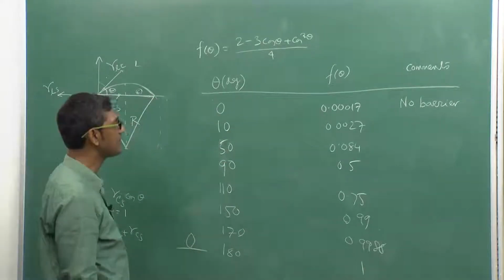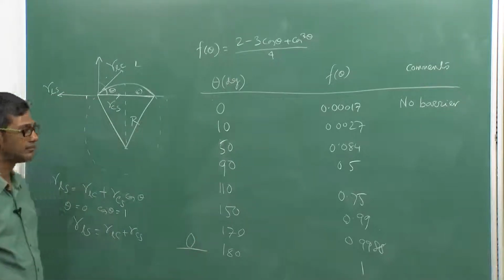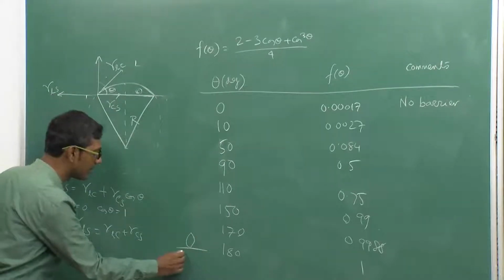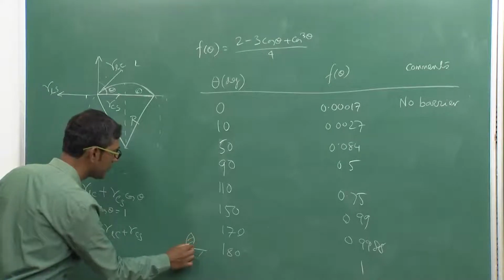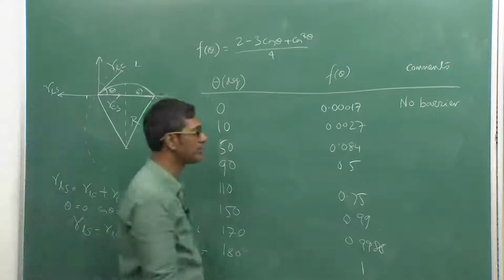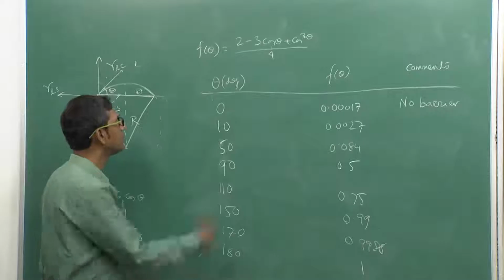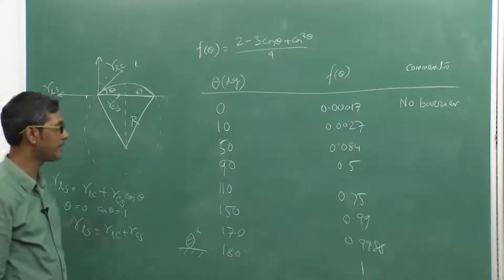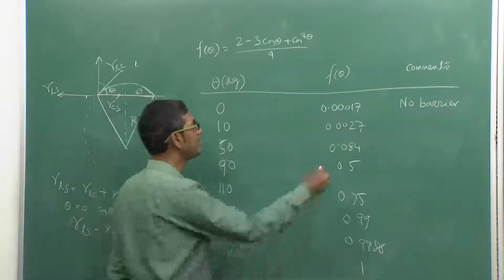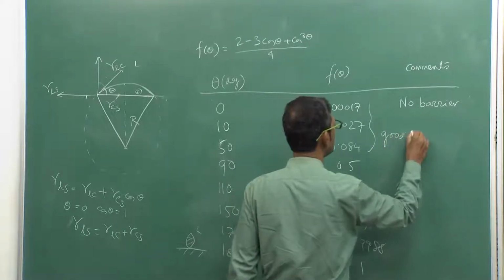So as you clearly see, there is no barrier reduction. The barrier is the same when the crystal is hanging on the substrate from the liquid. That means the barrier for homogeneous and heterogeneous nucleation is the same. There is no difference. But when it is 0 degrees, there is no barrier. So these are the situations of good heterogeneous nucleation.